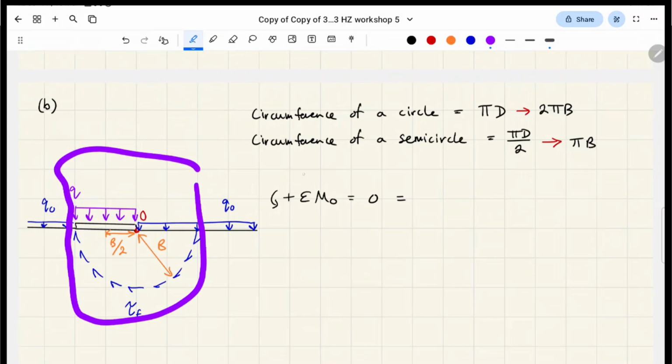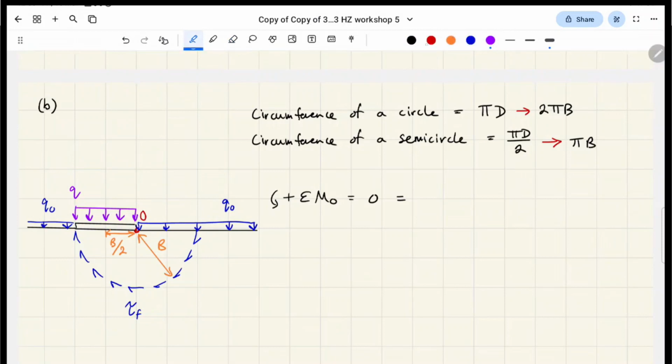So all the surcharge is happening off to the side. It doesn't actually affect our shear slip, essentially, right? What's going to happen is that this portion of the surcharge is going to help resist the soil failure, right? It's going to resist about point O. It's going to resist all the loading from whatever building or whatever this is from the footing, okay?